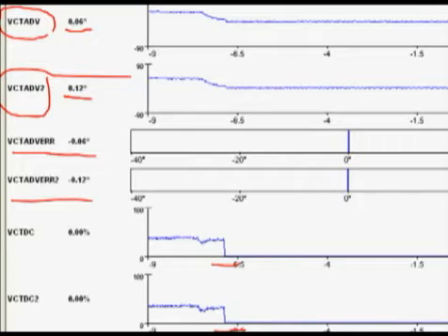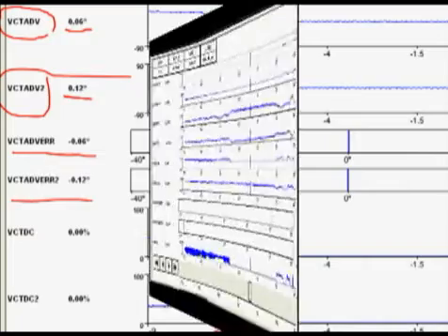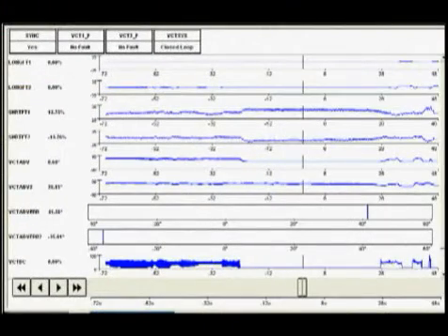And as we can see, everything's working properly right now. The blue bars are at 0 degrees. The VCT duty cycle, the duty cycle for the solenoids, is at 0, meaning that the PCM is trying to advance the cams, and it is being done. Well, now let's let the car run for a while at 2,500 RPM.